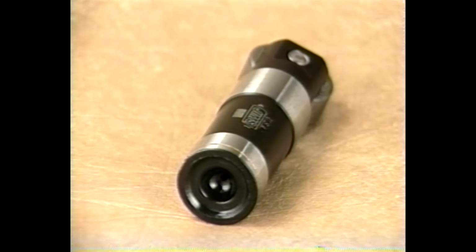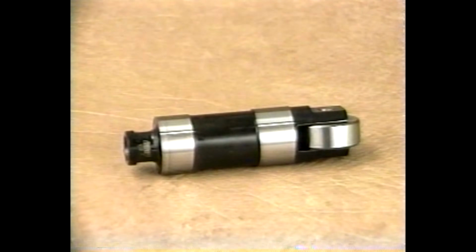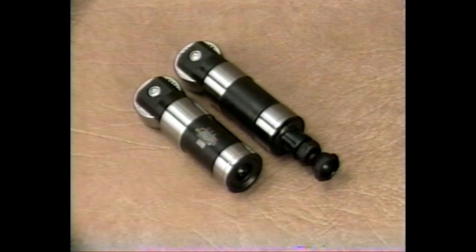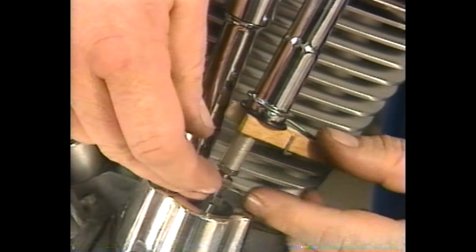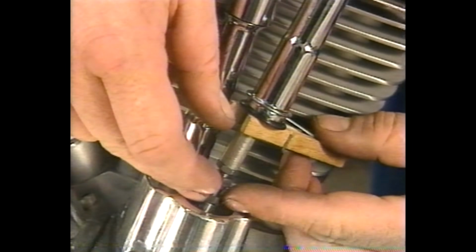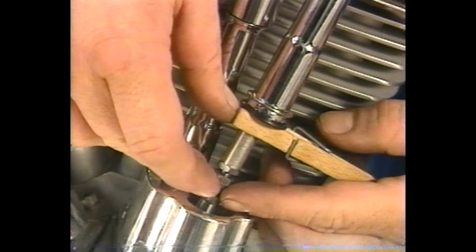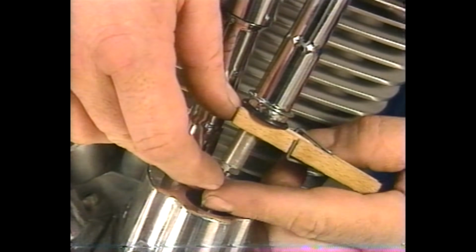Solid lifters are constructed in one piece and do not have any hydraulic damping units. Therefore, they will not overpressurize or collapse intermittently with oil pressure variations due to temperature or RPM fluctuations. Aftermarket solid lifters are lighter and are also available in shorter lengths. Use of shorter lifters reduces the excessive angles created when we use extra-long push rods in maximum performance engines that have longer cylinders than stock engines.